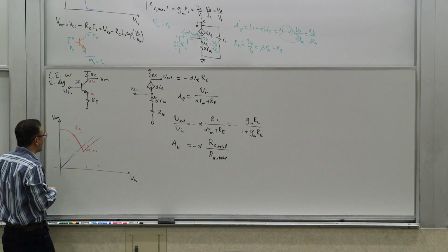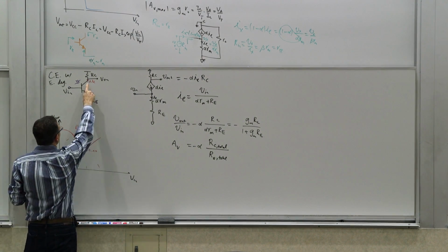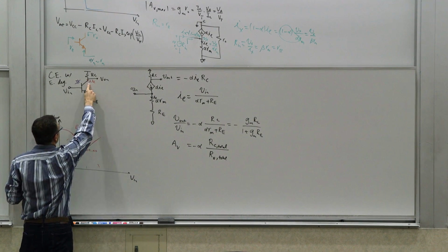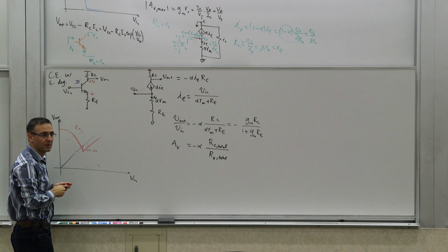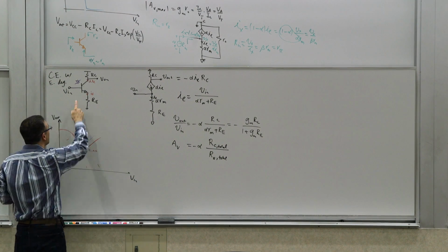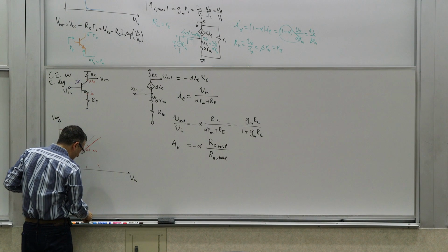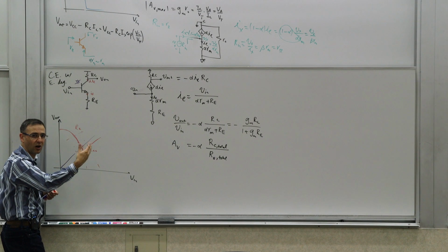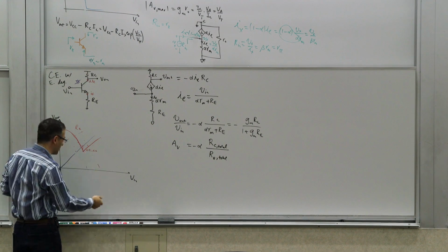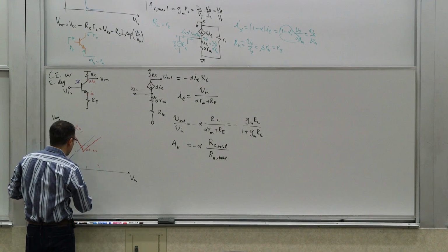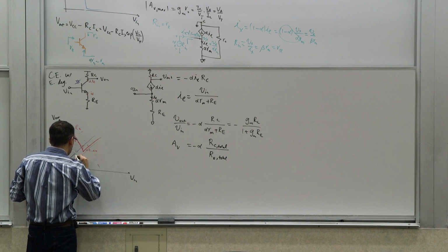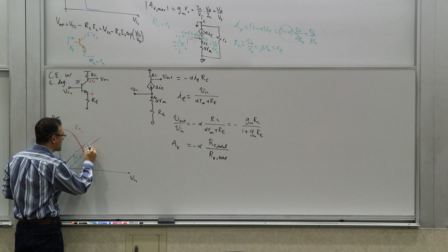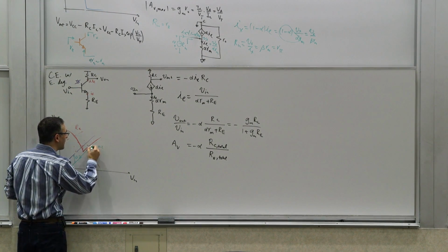Another way to see that is that essentially this voltage is going to be about 0.1 volts above the emitter voltage, right? What is the emitter voltage with respect to the base voltage? If the transistor is on, this is going to be 0.7 below it, roughly. It varies, but not much, because it's logarithmic. So that voltage is going to be here. This is where it's 0.7 smaller, so this is going to be 0.1 or 0.2 above that.